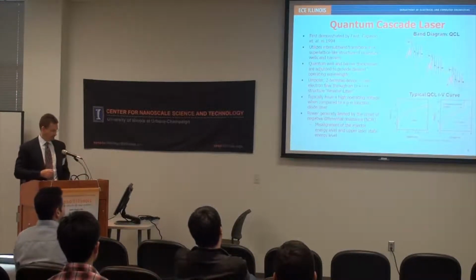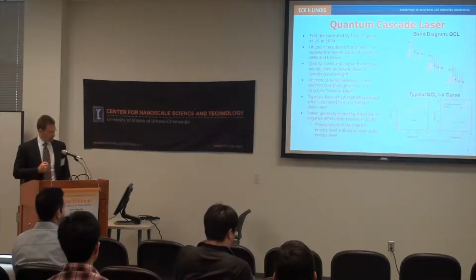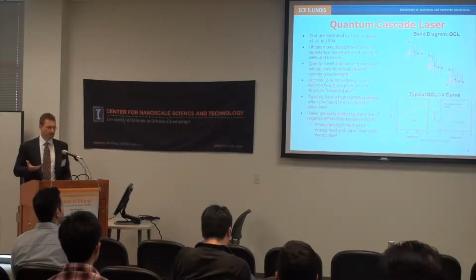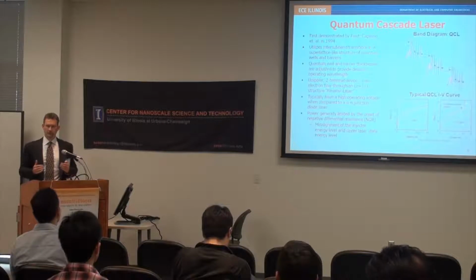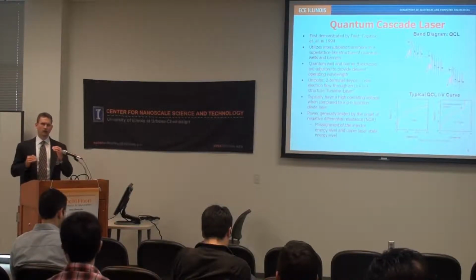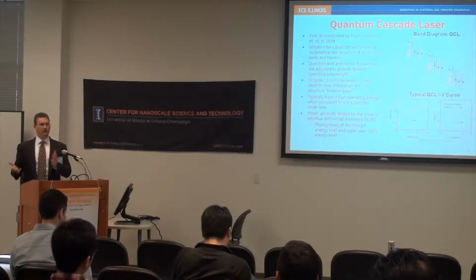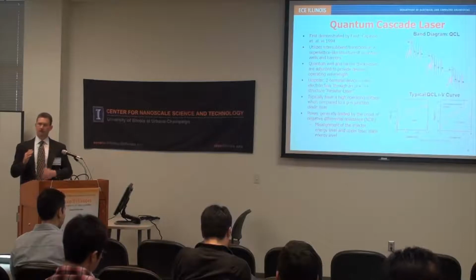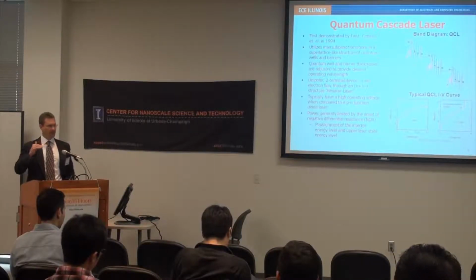So it's a very interesting device, but it has some problems. The biggest problem with the device is that it's a two-terminal device. We have this structure that we're producing, where we're relying on quantum transitions that we've engineered into this device. But when we change the bias voltage, we're changing the field across those regions. Changing the field changes the overlap between one state and the next.